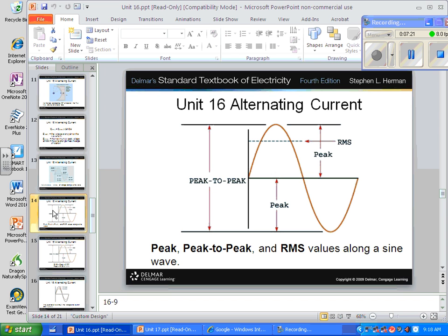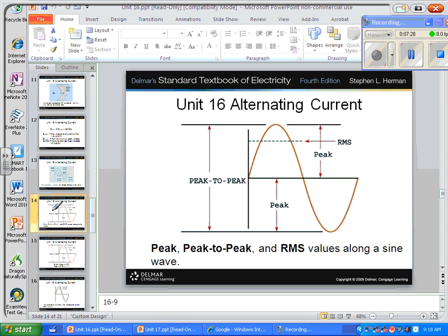Let me come back to that. So we have this wave of the power that's being generated, the voltage is being generated as it goes up. Now we're going to say this is 169 volts right here. All right? Now, this is called a sine wave because if you take the sine of any point along that rotation, because this is 0 degrees, right? This is 90 degrees. This is 0, effectively 0 again, right? It's 180. Down here is 270, which is the same thing as 90, right? And up here we're back to 0 or 360, right? So we've gone from 0 to peak back to 0.